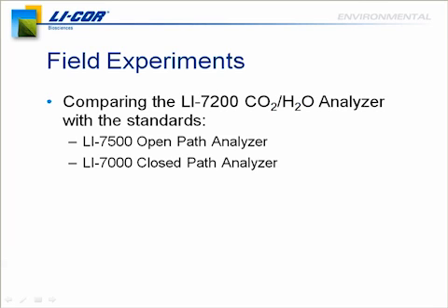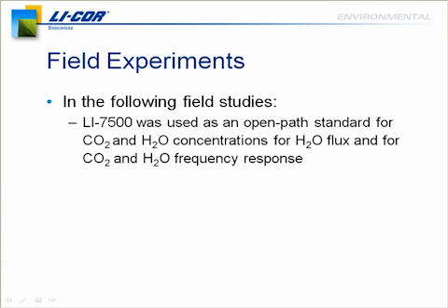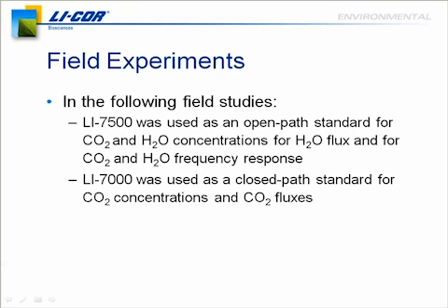What we're going to compare is the 7500, which is the open path standard for CO2 and H2O concentrations. We're going to compare the 7200 for the concentrations, the H2O flux, and also the frequency response for both CO2 and H2O. The 7000, which has been the standard for a closed path analyzer system, we're going to compare the 7200 for CO2 concentrations and CO2 fluxes.